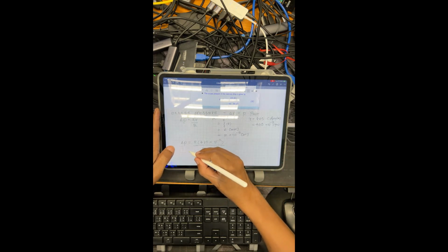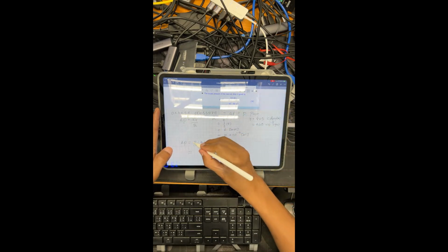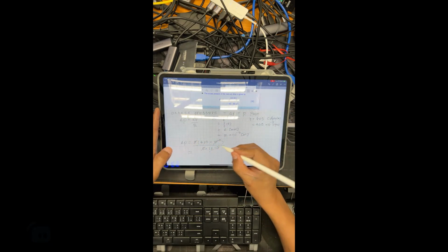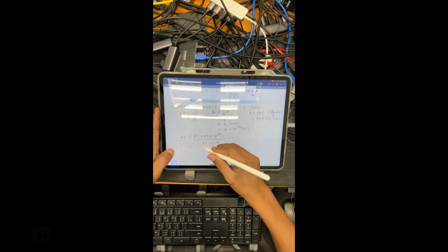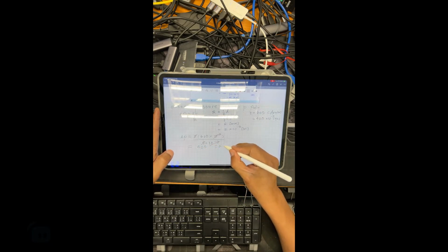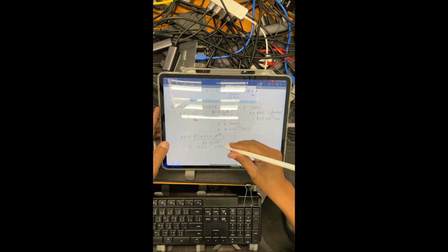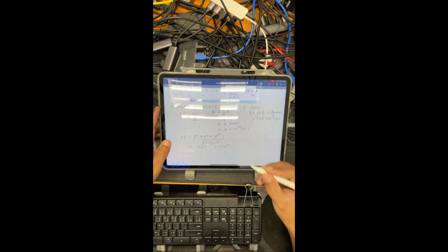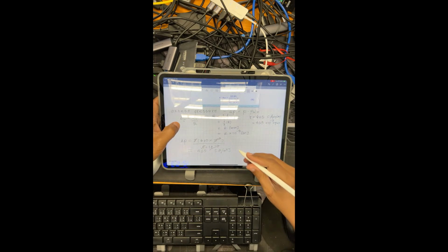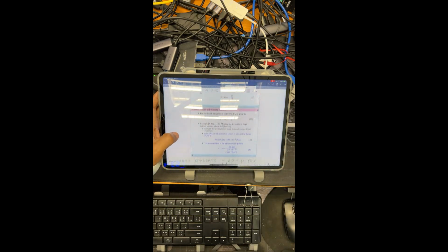You can see that 2 and 2 can cancel, and also this pair 10 raised to negative 3, and it's equal to 465 Newton per, as you know, Newton per meter for gamma, but gamma is again divided by a distance in meter, so this one is going to be square meter. So that's it for the basic formula in liquid drop, and pressure excess means the pressure difference.